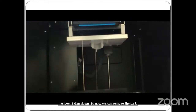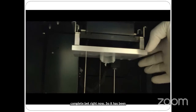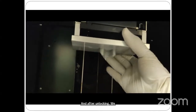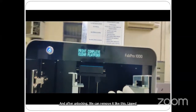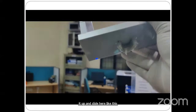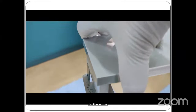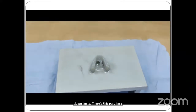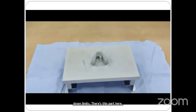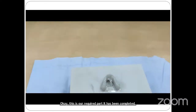In order to remove the part, we have to remove the complete bed right now. It has been locked. Unlock this bed, and after unlocking we can remove it like this, lift it up and slide it out. This is the bed on which our part has been built upside down. Let's place this part here. Okay, this is our required part. It has been completed, just there is a small extra cured portion that we can remove.